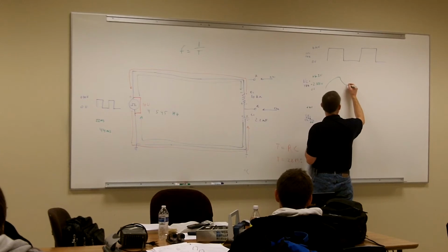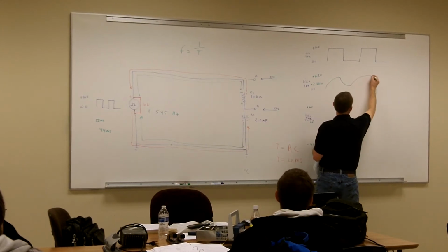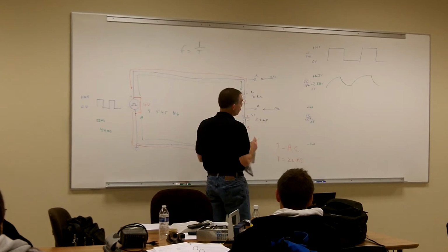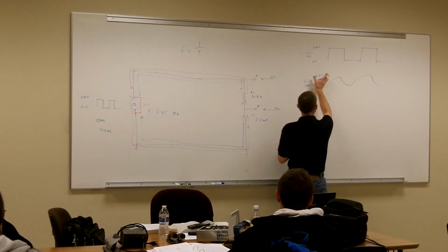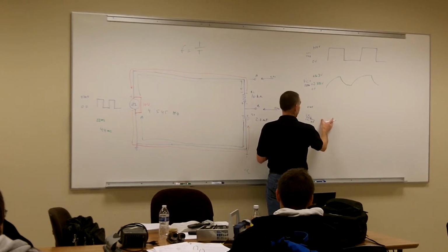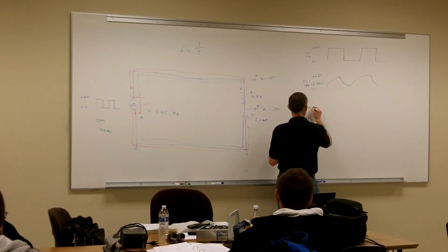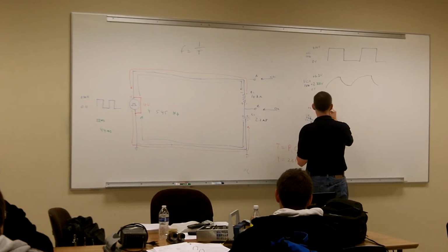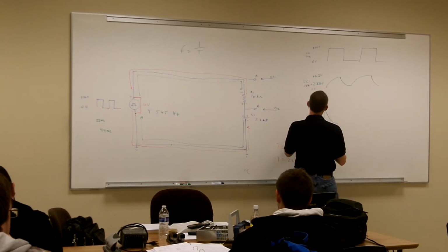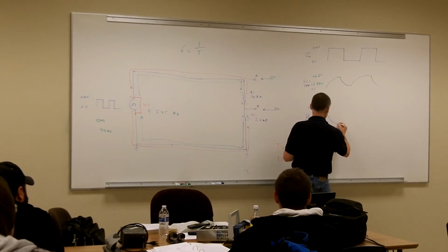And when I transition again from a low to a high, it's just going to go up to the 6.3 volts and then discharge down to the 2.331. So it's never going to get down to 0 volts. It's going to stay between 6.3 volts and 2.331 volts. And so the voltage across my resistor is only going to go up to positive 6.3 volts, then discharge down to 2.331 volts, and we just keep repeating our cycle.